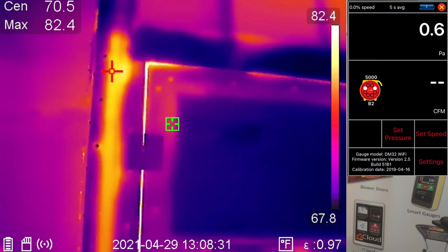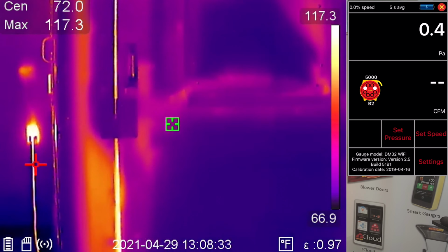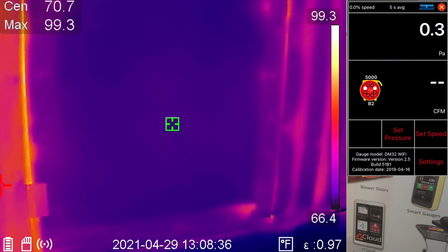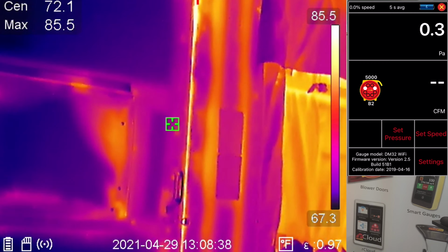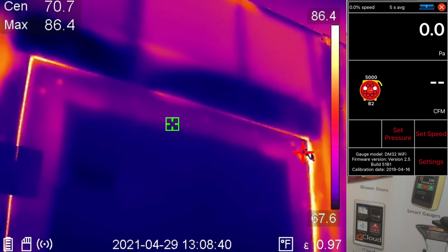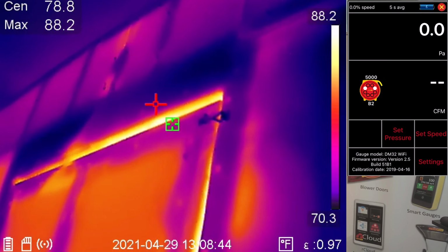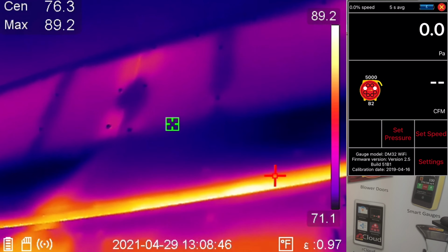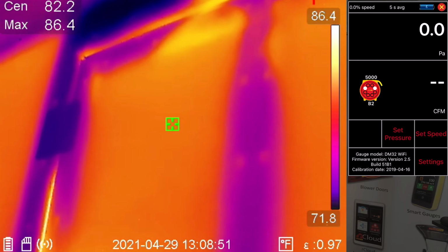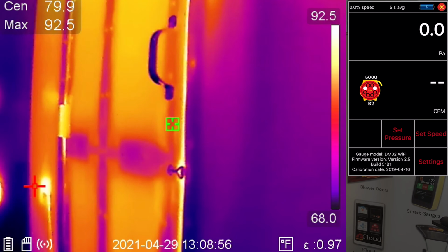It's because the surface temperatures around those areas that have been leaking have been warmed up by that interior air escaping. So we can still see this spot leaking where we didn't before we turned the fan on. Same for this panel here. These are still pretty vivid. Same around the leaks for this panel and this front window and this front door.